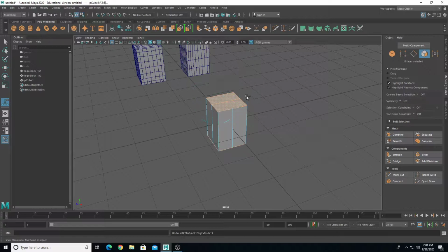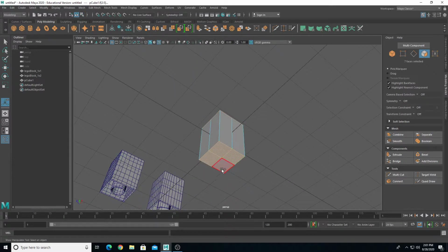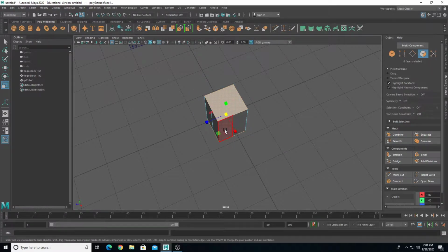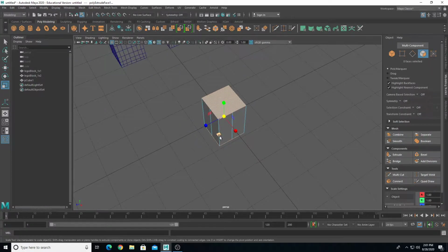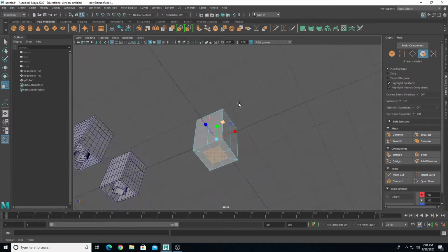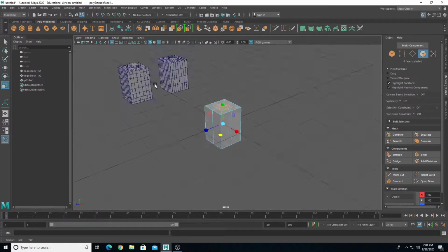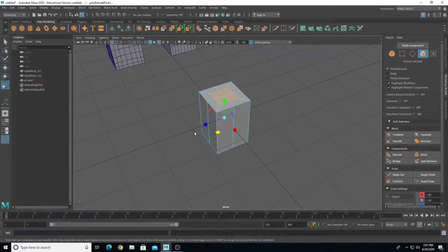I'm actually going to undo that and we'll extrude again. So I only want to have one extrude right now, and I can use the manipulator, but I'm actually just going to get the scale tool. So if I get the regular scale tool, and I'll make sure I use this green square on the side, and that's going to scale things in kind of an inset evenly on both the top and bottom. You don't have to extrude out multiple different areas, but I'm doing this because I know I need to have a cylinder on the top and the bottom there.